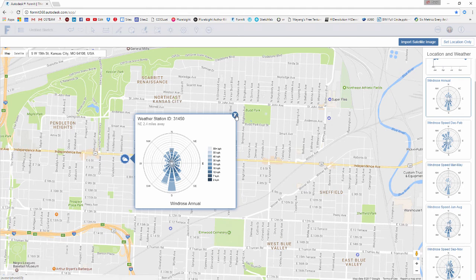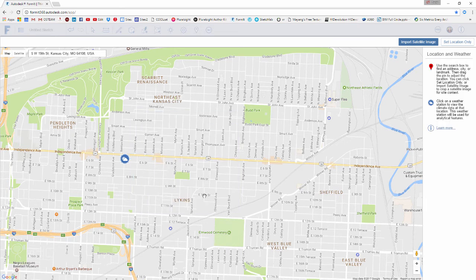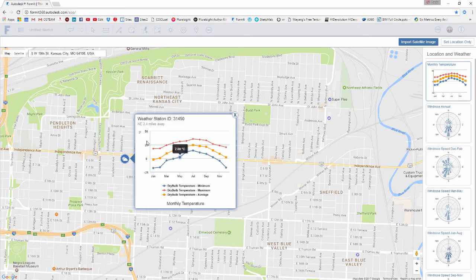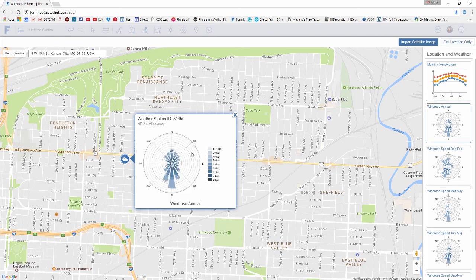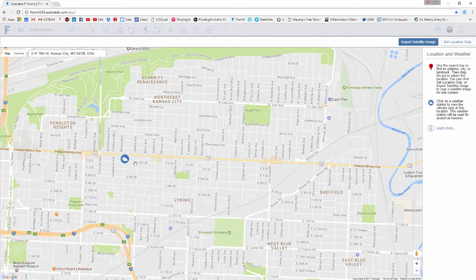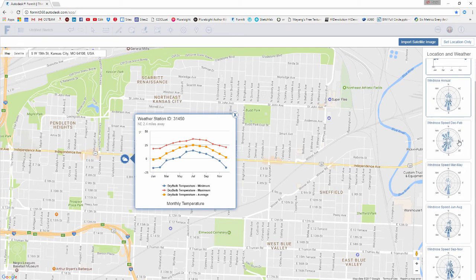But when we're designing in the Midwest, we have these massive temperature swings, as you can see in this base weather data right here. We have these massive swings in temperature. And so there are times of the year where we have winds that we can capture, and there are definitely times of year where we want to be able to block the wind. So in the Midwest, with these massive temperature swings, this wind rose is somewhat useless, really, to just be honest about it. So they have a breakdown for us on specific months.